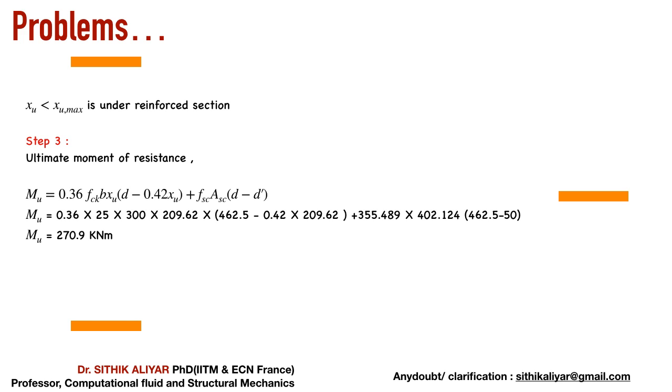So when you are solving any exam, RRB, any type of exam, and you get some answer around 400, 500, it's stupid, it's wrong. So you have made a terrible mistake. So please remember, more than formulas, try to memorize the answers also. What can be the range of your answer? What can be the range of steel? You cannot have an AST value of 4000 mm square for a residential building. Obviously, you see the beam dimension, you can never have 4000, 5000 mm square. And for ASC, you cannot provide 1500 mm square. It's stupid. So you should also know the answers like formulas.